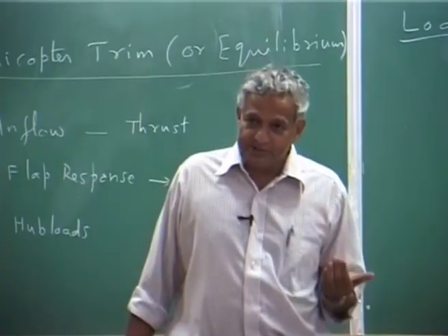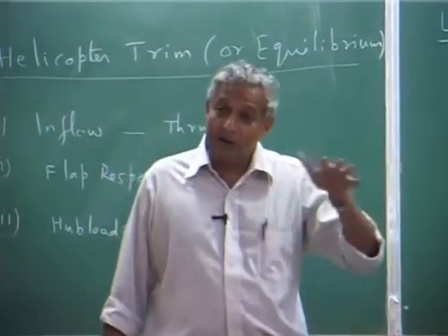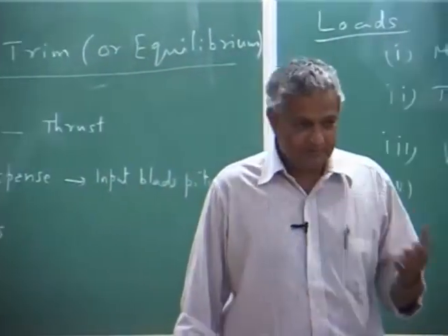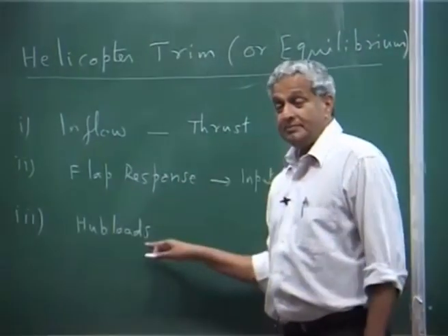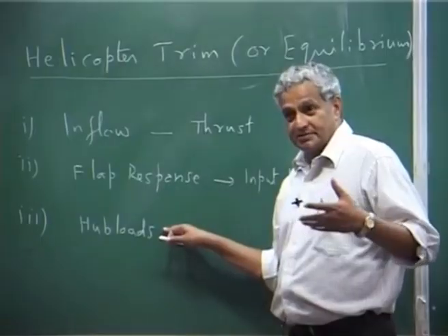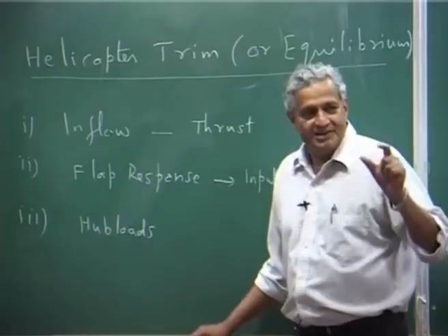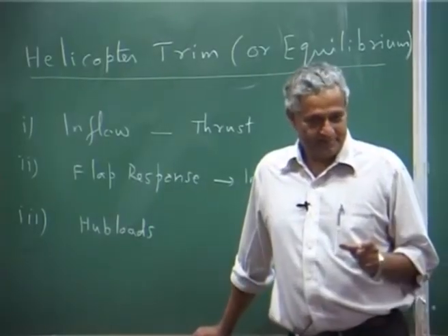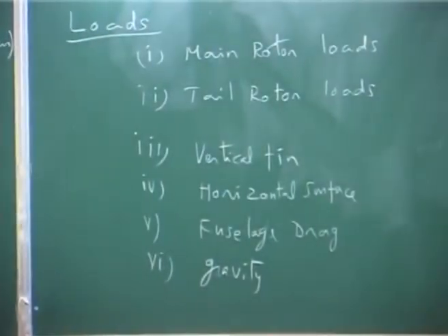Whether you want to write the equations in earth fixed coordinate or body fixed coordinate, you have to be very clear about that. All these loads are obtained in the body fixed coordinate system. So, it is always preferable to use body fixed coordinate system, transfer all these loads to that and then write the equations.